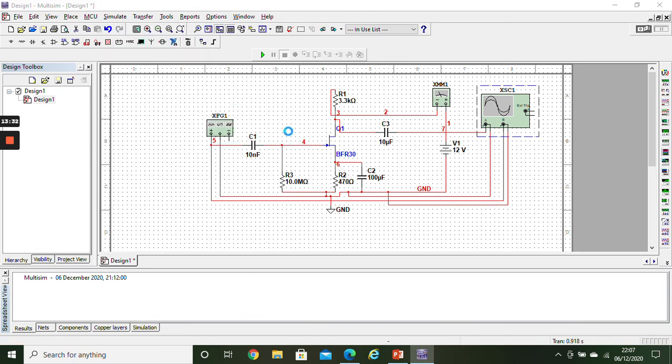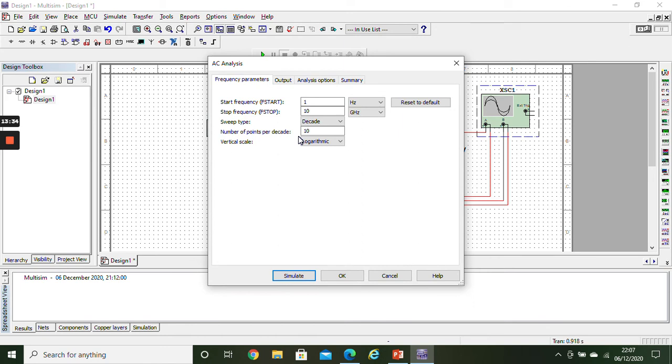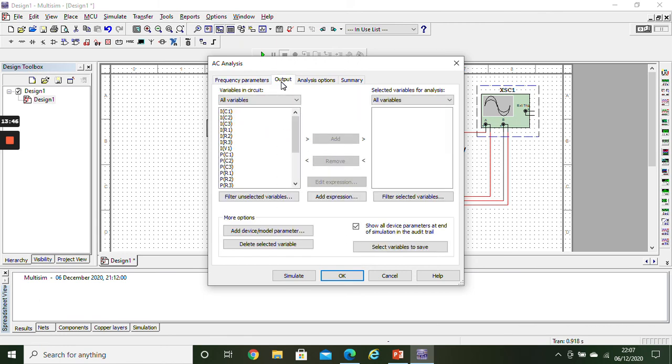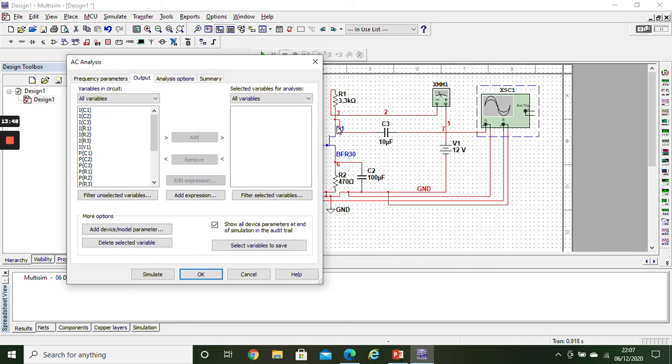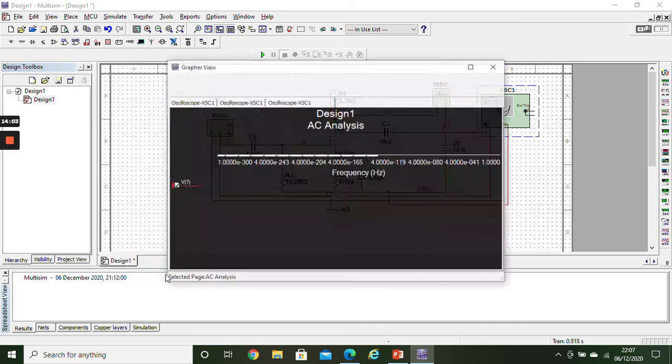Now I've changed it to AC, this is IDAC, ठीक है। And finally I will move towards simulation and analysis, go for AC analysis. Now this is for your response, ठीक है। Drop it down to 0.001, right, and instead of logarithmic, dB आपका जो scale होता है use it, ठीक है। Output में you will be specifying your output voltage. Now you can see this voltage, your this node number is 7, it means V7 is the voltage जिसका मैं frequency response check करना चाहती हूँ, ठीक है.